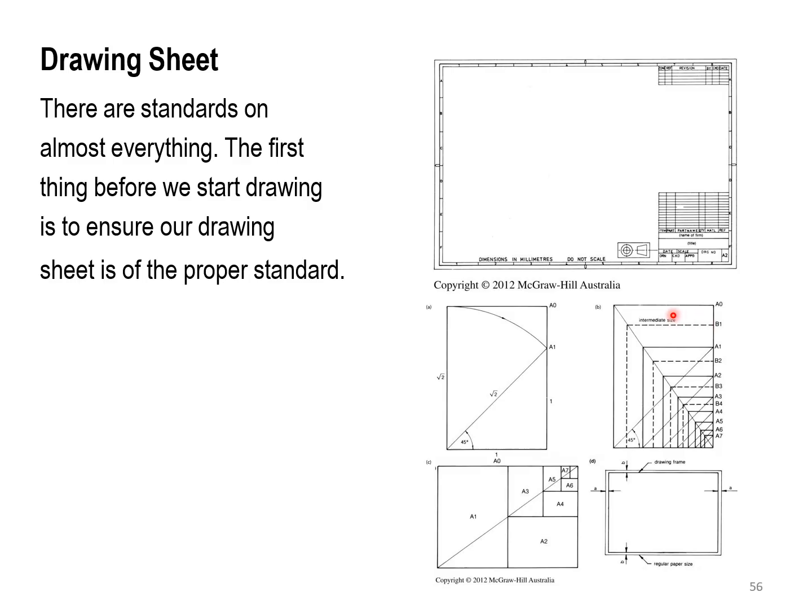These are the different sizes of the papers, starting from the A7 up to A0. A0 is the largest, and the A7 is going to be the smallest. Usually the engineering drawing is going to be done on A4 paper and go up. You can see that each time, the A4 is half of the A3, the A2 is double the A3, the A1 is double the A2, and the A0 is double the A1. And also we do have the B type. You can see that the things have been shown on this diagram.